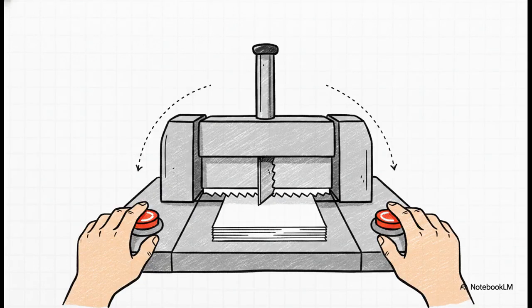Step 1 is hazard avoidance. And frankly, this is the gold standard. Here, you design the system so the hazard is just fundamentally impossible. For example, think of a massive industrial paper cutter. A major hazard is the operator's hands being under the blade, right? So how do we avoid it? We design the machine so it physically requires the operator to press 2 completely separated buttons simultaneously using both hands just to bring the blade down. By design alone, we have entirely avoided the hazard of a hand being in the way.